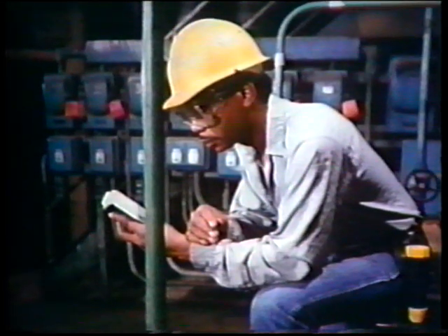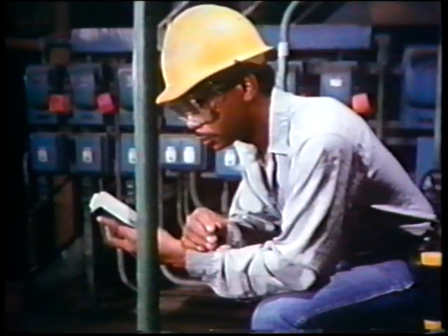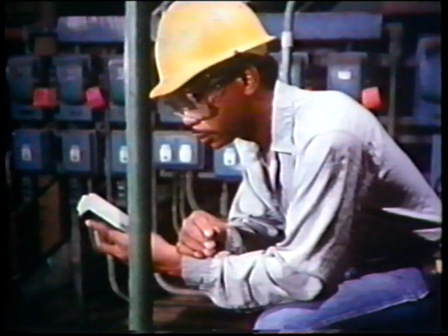Just as there are different maximum operating temperatures, there are different voltage ratings. For example, a particular type of insulation may have 4 different ratings. It may be rated at 250 volts or 600 volts, or 1,000 or 2,000 volts, depending on its thickness. You should always be able to see the voltage rating of a conductor's insulation stamped right on it. And you're going to have to check the rating on the conductor against the operating voltage of the circuitry to be sure the rating is high enough to do the job.